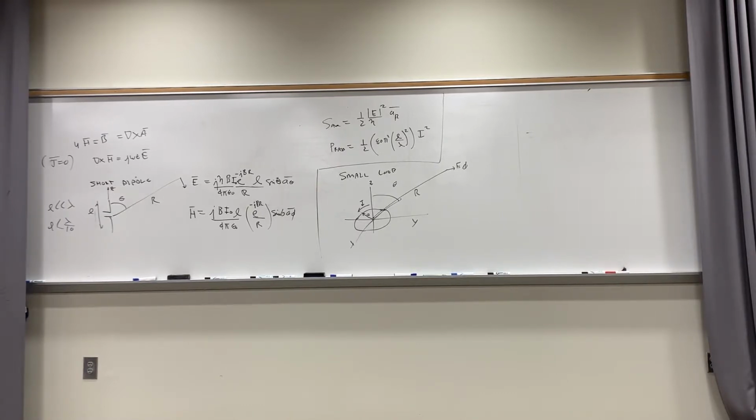Peak power and no power as it rotates through. Because a polarization filter allows only light, or I should say electromagnetic energy, of one polarization to get through. So if the filter's allowing energy polarized this way, and I move my antenna this way, nothing gets through. You follow me? And that's real important. That's a polarization filter.